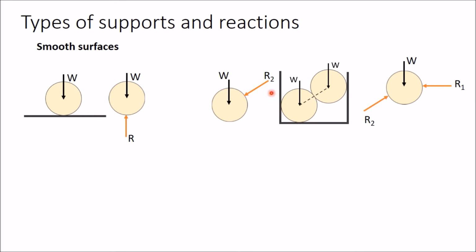Now you must remember that whatever name you have given to this R2 here, the same name you should give here also, and whatever direction you have taken, you have to take the opposite direction. So you have taken the upward direction, so here you must take the downward direction, that is compulsory, and the same name you should give to both the reactions because these are action and reaction forces.